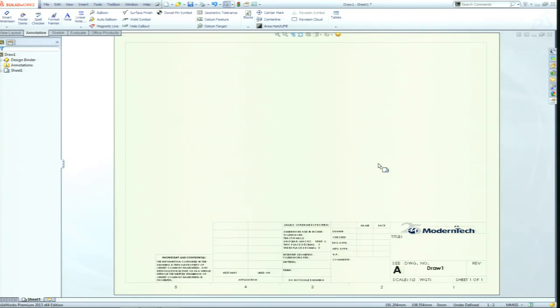All right. Now, guys, and kind of to reiterate, the drawing sheet format is only a sketch and text. That's all it is. So if you have a DWG, if you have a picture that you've got as your text, you can go in there and actually copy the whole thing as the sketch and bring it in to a blank sheet and paste it on top here, and then go in there and size it to make sure that you have the right size and to give yourself the right look that you're looking for as far as a company. Okay. Any questions about doing that?